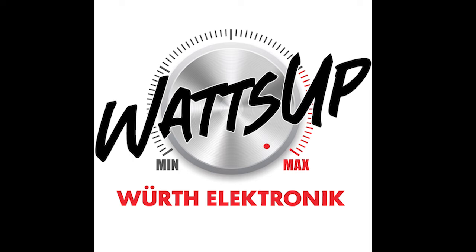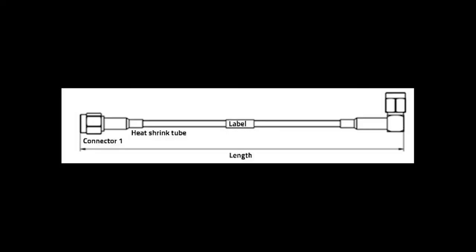Worth Electronic offers a made-to-order cable assembly service, which reduces the user's assembly workload and manages the requirement of reliable signal transmission. So here's what to consider and what's required information to get a cable assembly. First, connector 1 and 2. Check the interface, orientation, or ingress protection function. Second, heat shrink tubes. Check specific length, color, or customizable text. Third is the label. Apply the standard Worth Electronic part number or customize the content or add a special label. And last, check the definition of length.